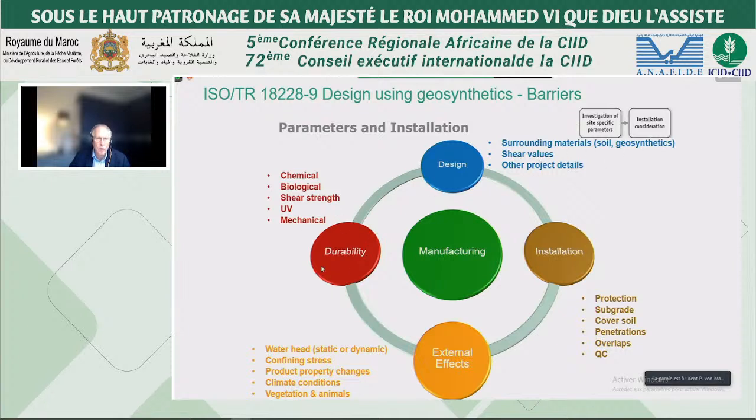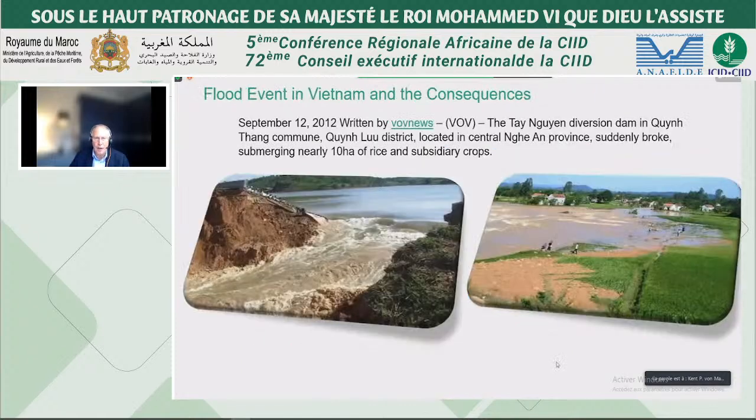It also considers the durability, chemical, biological, or shear material, and the external effects as well, because they can be totally different in different countries. As we've seen, you can have cows walking on the material, you can have animals digging through your soils, you can have different types of vegetation in the area, the climate conditions are different. So all these effects have to be considered in your design phase.